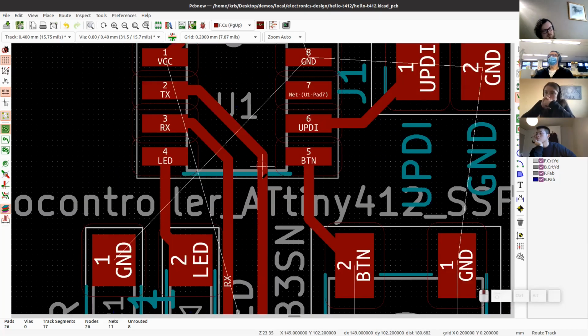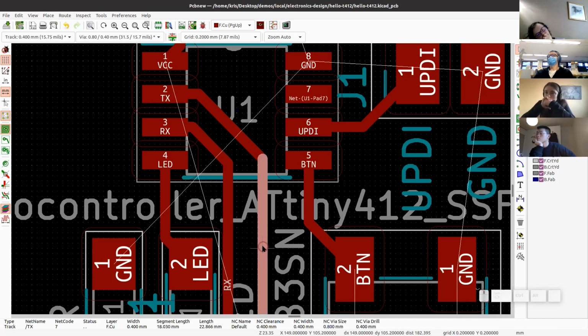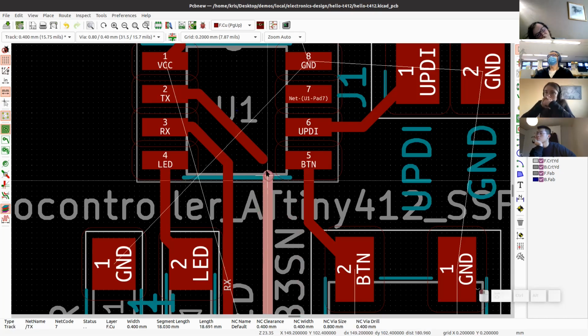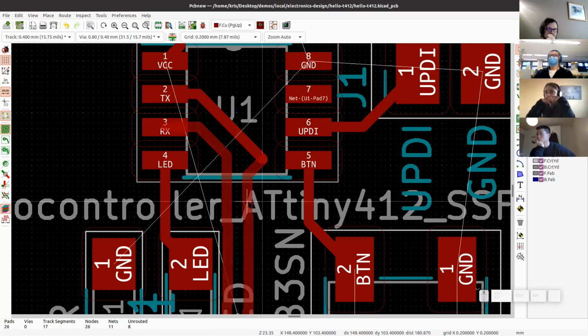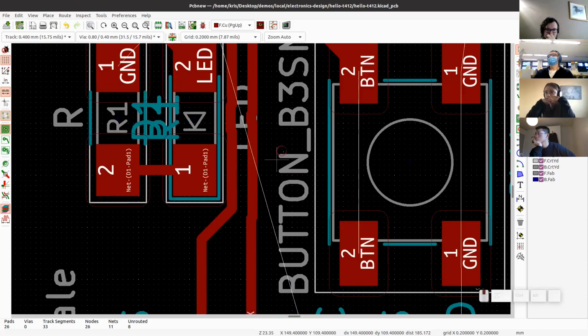If you don't like the layout, there are ways to move those. It's not really as straightforward as Illustrator, because when you move around a segment of the track, it sort of loses connection with the other ones. So if you want to keep it in place, then you should use the drag tool, and you can access that by selecting the track that you want to edit, and then hitting D. It's going to drag the respective points and lines to match your design.